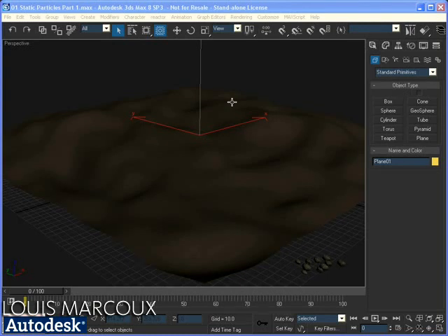But you can also use particles if you have way more objects to distribute. Always think in terms of particles when you want to have a lot, like thousands of objects being distributed in a scene. If it's just a dozen or a couple of dozens of objects, you can go with Reactor or use other techniques. But particles is very, very oriented toward a massive amount of objects.